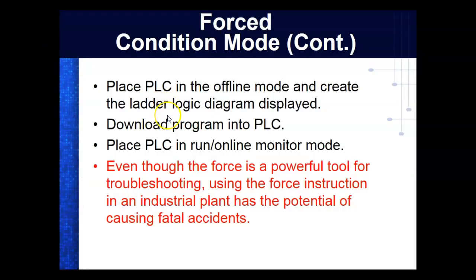So technically on this thing, even though the force is a powerful tool for troubleshooting, using the force instruction in an industrial plant has the potential of causing what? Fatal injury. So when you force a contact out there in the real world, in the Navy, when we were going through our A school and C schools, they say, this is the way we do it in school, but when you get into the fleet, you've got to be careful with this.